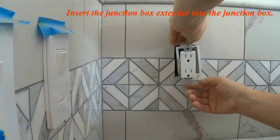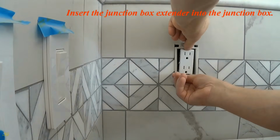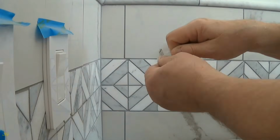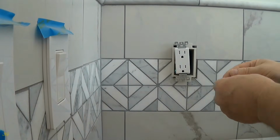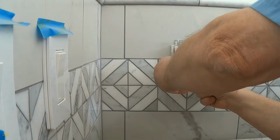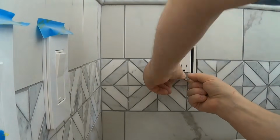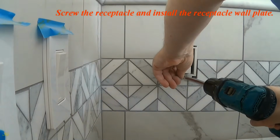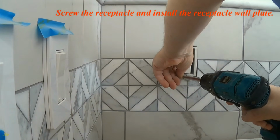Insert the junction box extender into the junction box. Screw the receptacle and install the receptacle wall plate.